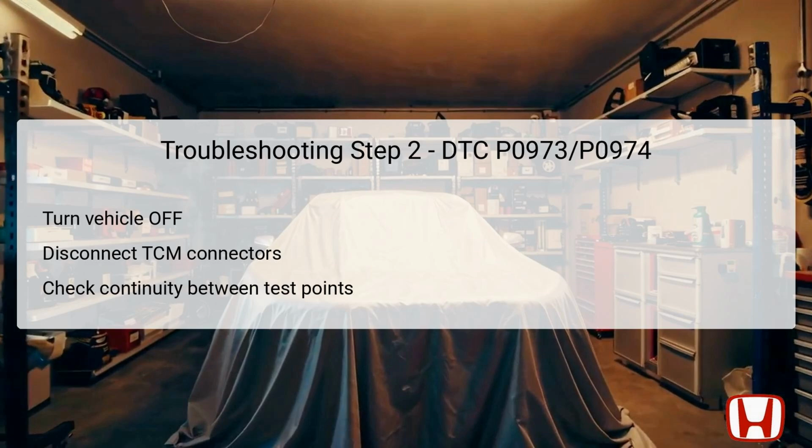This involves using a multimeter set to the continuity setting to verify if there are any breaks in the wire. If continuity is present, it indicates that the SHA, shift assist, and VBSOL, valve body solenoid, wires are intact and not open in the circuit. However, if there is no continuity, this suggests that a repair is needed to fix an open circuit between the sensor unit and the TCM.